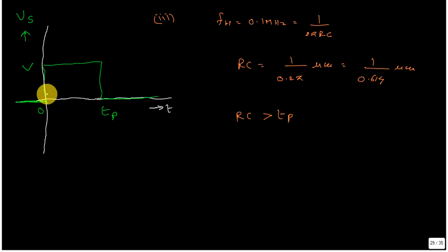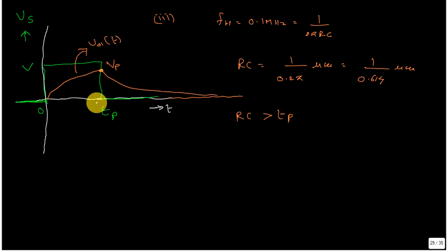So definitely the capacitor cannot reach the final value; the capacitor reaches some arbitrary amount. From this, the capacitor discharges towards 0 after taking a longer time. Okay, now we need to calculate the value of Vp. Vp can be calculated only if you know this voltage waveform, that means V01 of t. So first step is you must calculate V01 of t.